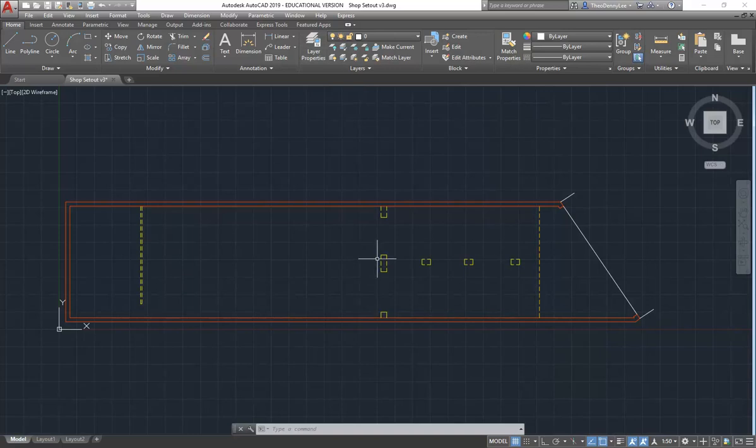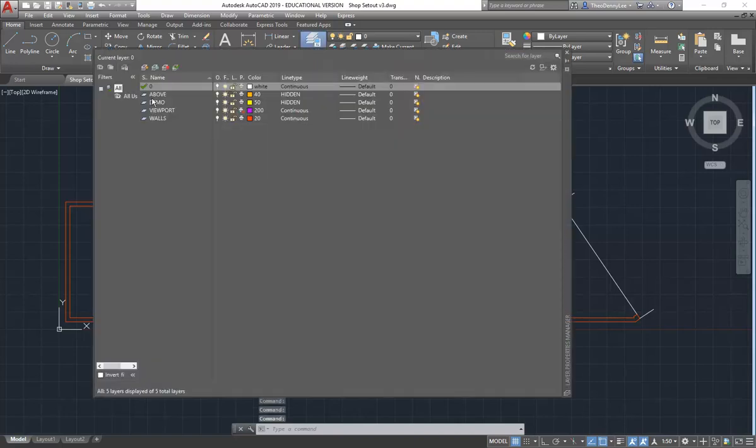And so the problem now is that this dash line should have smaller dashes again. Do you know what the smaller dashes mean? So this big dash normally means it's below, and the small dash means it's above. That's the basic convention.